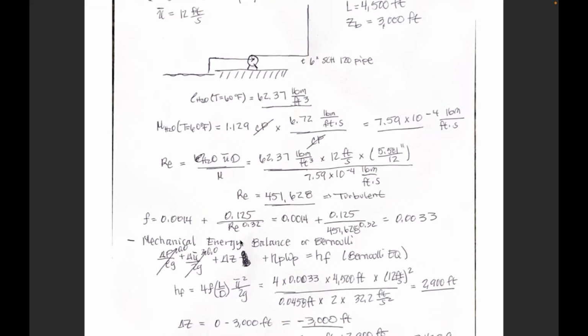And so out of that same book, there's an equation for a range that you can solve for f, the friction factor. And so that's what I done here. Plug in the Reynolds number, or you can use, what is that? I think in y'all's courses y'all probably use the Colebrook equation. I didn't put that in there because it takes too much work. But that'll give you a more accurate answer than what I have here.